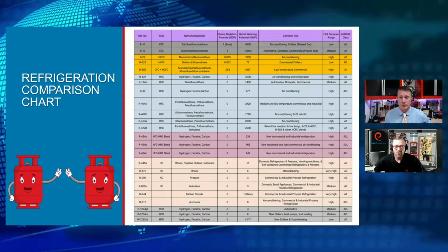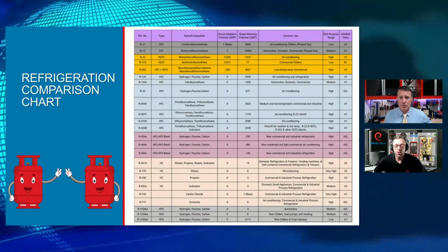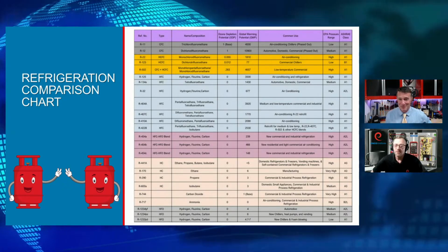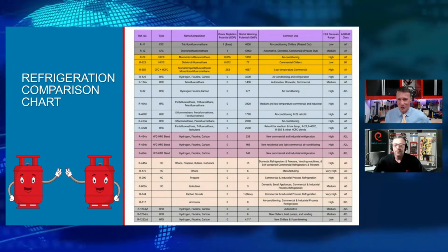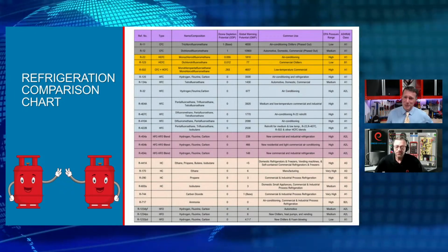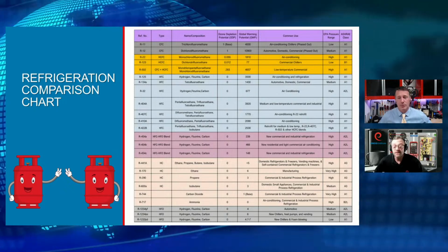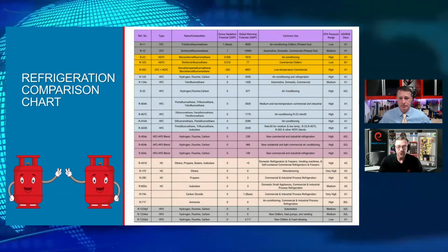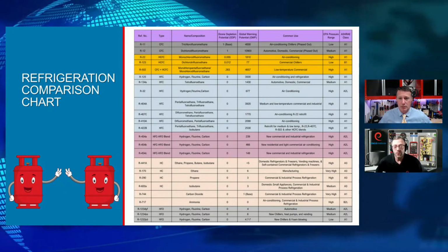One of the things that we noticed with the previous generations of refrigerants is that you would see one refrigerant used across 7 or 8 different applications. We used to use R12 everywhere. We used to use R22 in everything: cars, freezers, coolers, walk-ins, stationaries, Coke dispensers. I mean, you named it. So we're going to start to see more application-specific refrigerants, where this refrigerant is used in this application and this refrigerant is used specifically here. We're going to see a lot more of that moving forward.